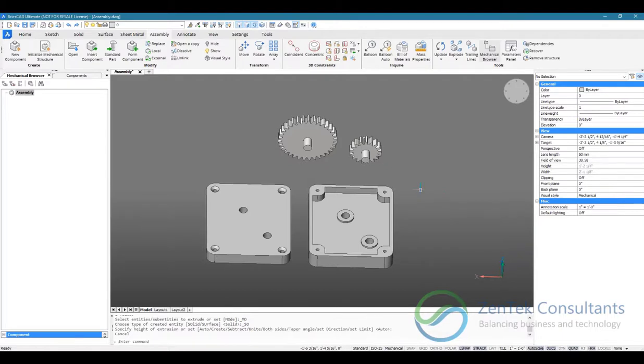So unlike SolidWorks and Inventor, where components and modeling objects and parts are handled separately, and they have two separate part names, BricsCAD handles this in the same environment, in the DWG modeling environment. So to distinguish components from regular 3D objects, they're turned into blocks, similar to how 2D line objects are turned into blocks to group them together and duplicate them. BricsCAD goes a step further with this, as it turns them into blocks and it assigns them mechanical structure.